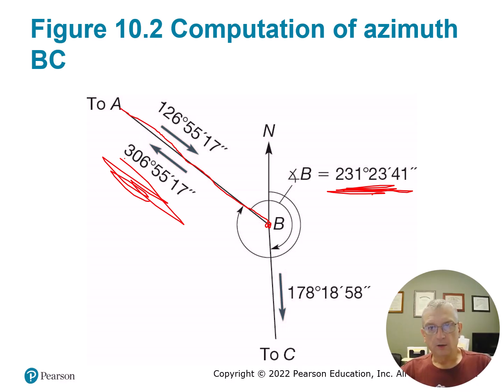That's all. Where this does come into account is when we adjust and minutely bump that error out until it basically goes away or is equally compensated for. Our angle turned at B might turn out to be 44 seconds instead of 41, so this might change our azimuth. We would love to just look at our figure, compute our raw angles, compute our angular error, then adjust our interior angles, and compute our azimuths only once.